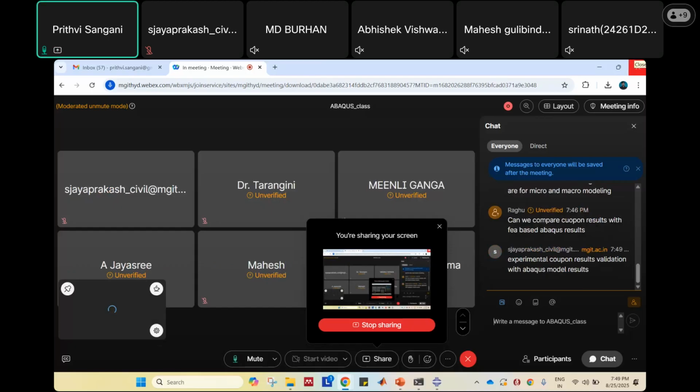Fine. I think I'll answer that question also, Raghu, because right now I can't directly jump into that. Anyways, I have planned for coupon test results as well. But just to answer you shortly, in FE analysis, when you're analyzing, you should definitely give a material property to the model, right? So what material property are you going to give? You are going to give a material property which you get from the coupon test. So you are giving the same material property and trying to get the same material property back, right? That's kind of weird, but fine. We can have a comparison for that as well.